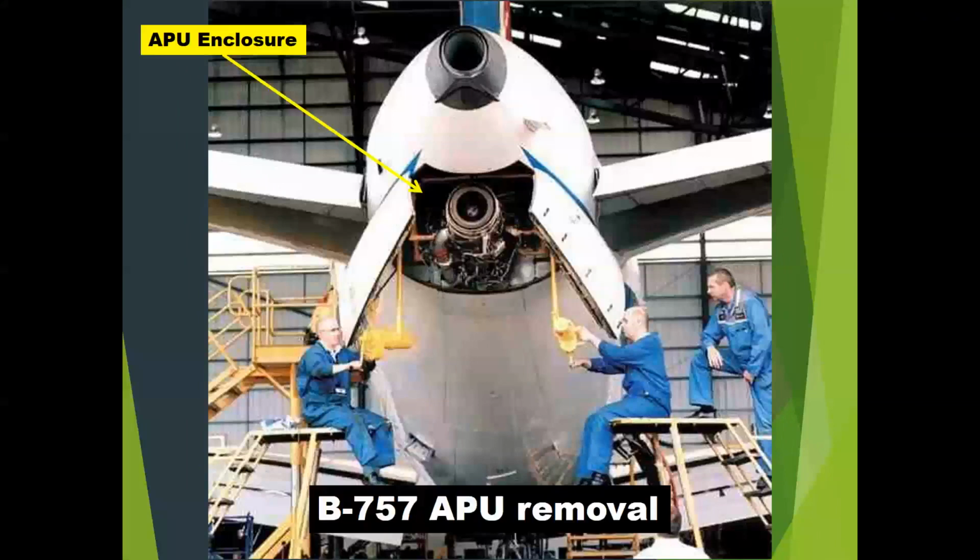You remove the mounting, and then the two technicians sitting on each side will evenly crank out cable to lower the APU out of this enclosure. So rather than having to lift it from the bottom, they're kind of a temporary crane you can install from the top. And that's a pretty common setup, using these fishing poles rather than trying to get a forklift in there or something like that. But as I mentioned, the real important part, looking at the tail here, this serves as the APU enclosure, creating that fire zone between the tail cone itself and the firewall at the front.